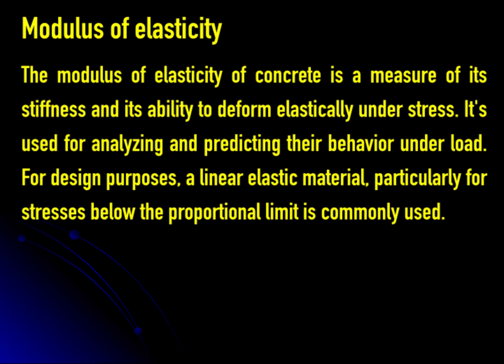Modulus of elasticity. The modulus of elasticity of concrete, also known as Young's modulus, is a measure of its stiffness and its ability to deform elastically under stress. It's a crucial property for analyzing concrete structures and predicting their behavior under load. For design purposes, a linear elastic material, particularly for stresses below the proportional limit, is commonly used.